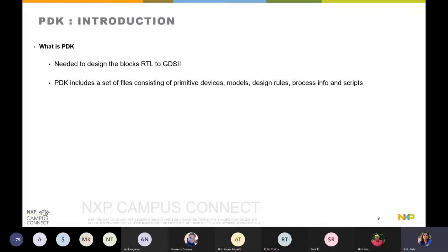Because this process data is provided by the foundry, it tells how the whole fabrication and the layers will behave once they are on the chip, how devices will behave when they are sitting next to each other or on top of each other, or at what part of the die the device is located. Also, multiple scripts are provided based on the design team's requirements.